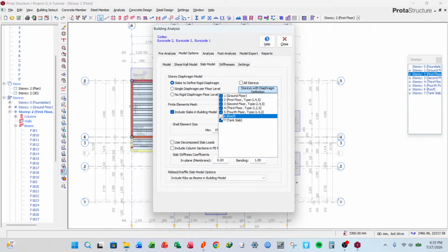So any wind load that hits the building at that level will simply be taken up by the individual elements. Yeah, that is a simple explanation I can give. Or the wind will actually just go to the roof, and later from the roof through the trusses, it will be transferred to the individual columns supporting the roof. Okay.